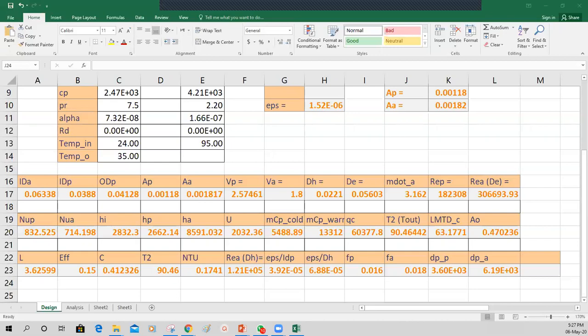15 degrees Celsius, yeah. It comes out to be something like 5.64 kilowatt. Yes, it's kilowatts. That means that you need a boiler for this condition of 5 kilowatt. And this is for a running boiler, right? That will work inline. Like you switch off the flow, your boiler is shut off.